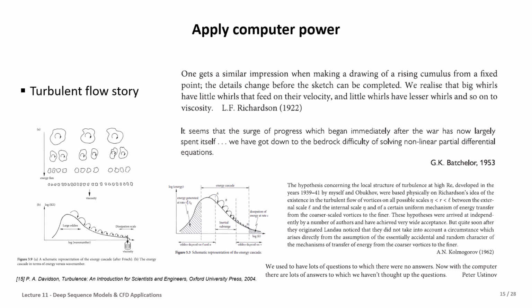In the large scale, the dominant feature is controlled by the large scale, but in the small scale, the dominant feature will be based on the viscosity in the fluid dynamics. These are fundamental concepts of the turbulent flow: how this process is happening, and how the initial condition, boundary condition, and the material properties are impacting the transfer of the energy between the different scales.